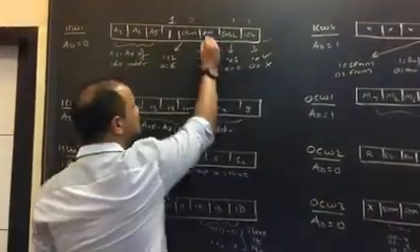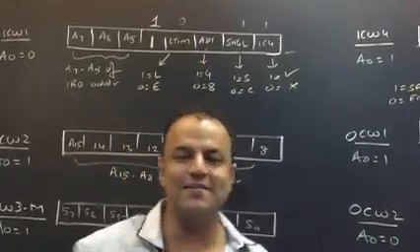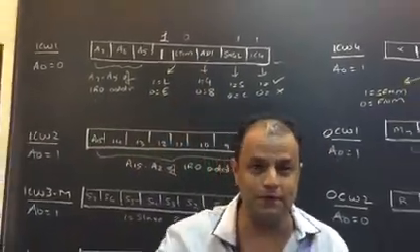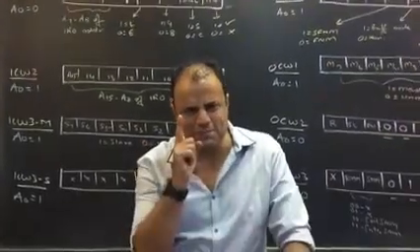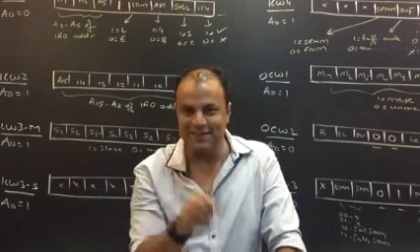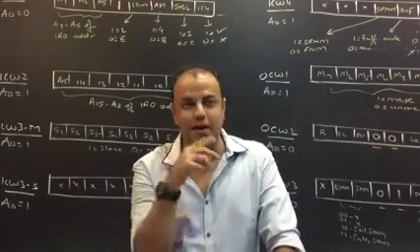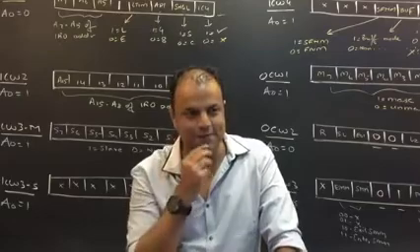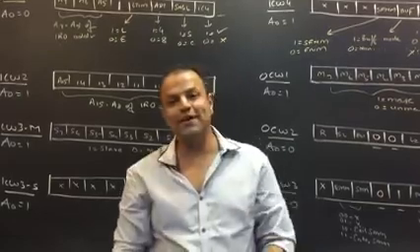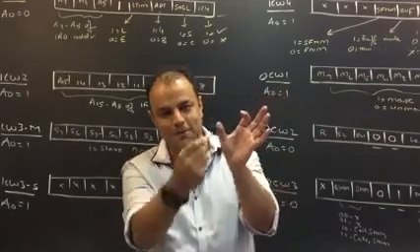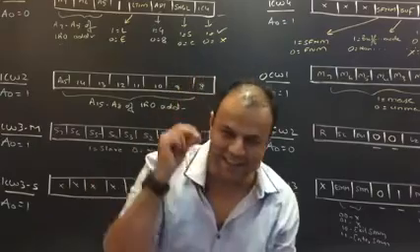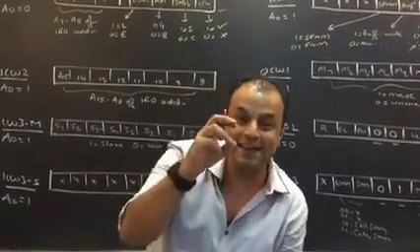Now, we come to this bit called ADI. ADI stands for address interval. What do you remember? I told you, when we initialize 8259, the most important thing we have to tell 8259 is the ISR addresses of the interrupts. Now, how many interrupts are there in 8259? 8. Do you tell 8259 the address of every interrupt? No. You only tell the address of IR0. The remaining addresses are taken in a sequence. Do you remember that or not? Exactly. Now, sequence means there is an interval.